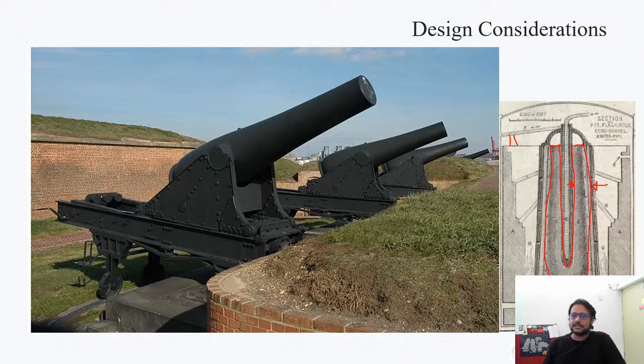These inner surfaces are the place where the cannonballs would be held. Because of the way in which the material cooled, you can imagine that there'll be a place at probably the center of this whole thing where there are chances of porosities, casting defects, coming into existence. Because of this, the earlier cannons were fairly unreliable. Once a few rounds were fired, cracks would appear, and the cracks would easily traverse through the surfaces, because this internal part was almost as hard as the external part.